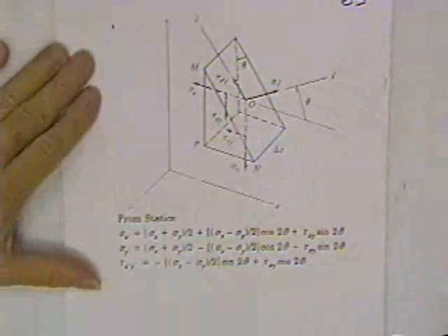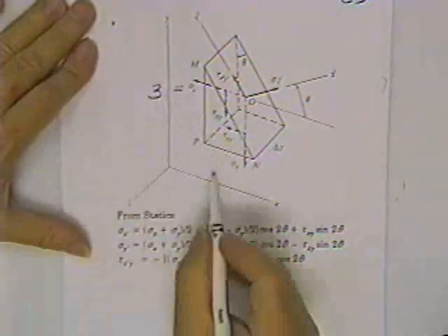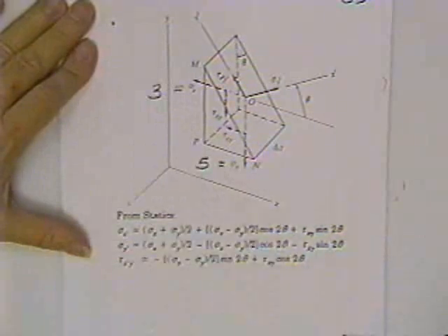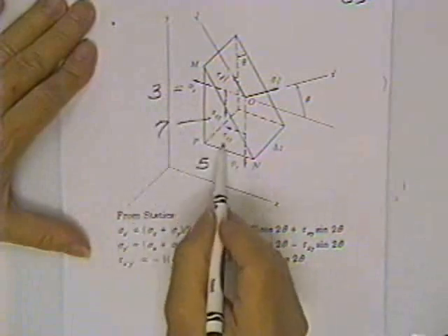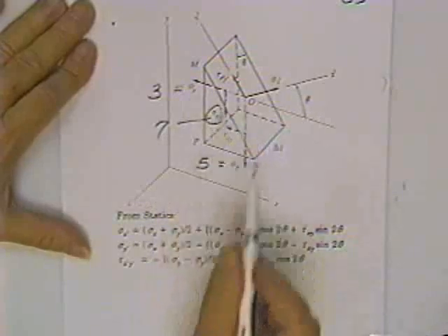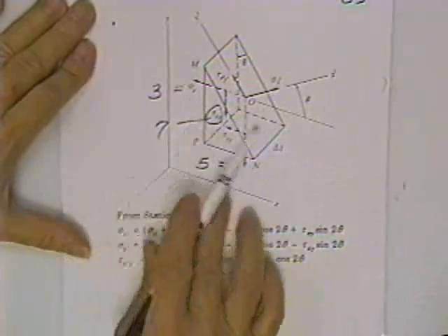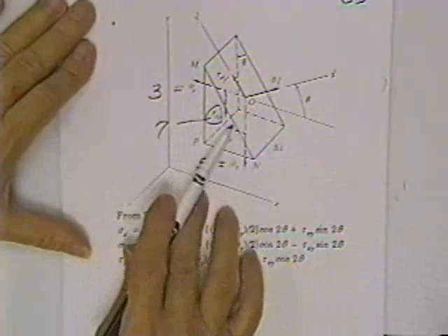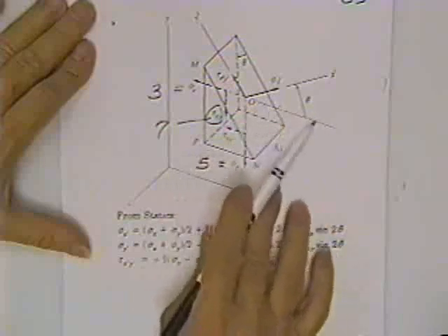If he asks you for the stress on any plane, you pretty much got it made. Because if you know sigma x is 3 and you know sigma y is 5, and you know the shearing stress right here is 7. If that one's 7, this one's also 7. There's 7 all the way around. Then you can find the shearing stresses on any new plane of your choice. Merely tell us how far these faces rotated from the vertical to the plane, or how far this rotated from this axis, and you just plug in.